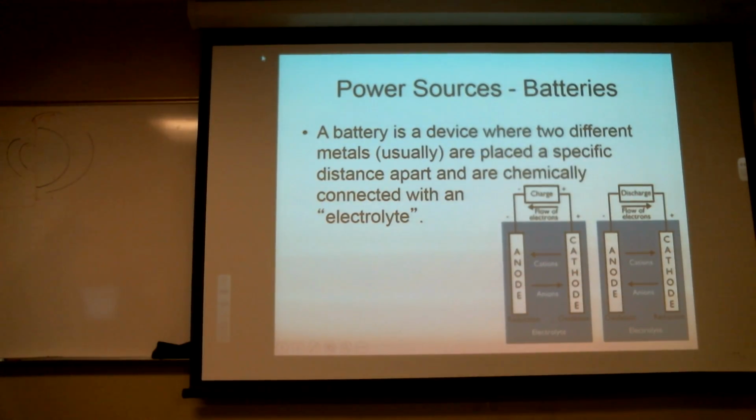The end result is, the other thing that needs to occur is in the chemical side of things, the individual plates cannot electrically conduct with each other. Okay? If that happens, the other plates will try to conduct in a closed loop inside the cell rather than going the other direction. Okay, so we have to keep these different, the anodes and the cathodes, all separated from each other so that the only electron transport occurs through a chemical reaction in the electrolyte.